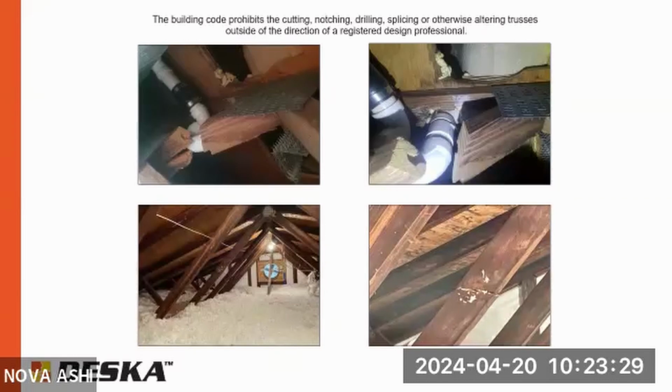the authority if it's not a truss, but rafters and rafter ties that can be compromised in an attic in terms of a repair? Somebody cut through either a rafter or a rafter tie. So if it's a rafter, that would be looked at the same as a floor joist or a ceiling joist. So it could be sistered. Whereas if you're talking about truss floor joists, it's a pretty detailed process to design the repair, and it typically involves sandwiching the trusses with plywood, a certain nail pattern, and gluing it.